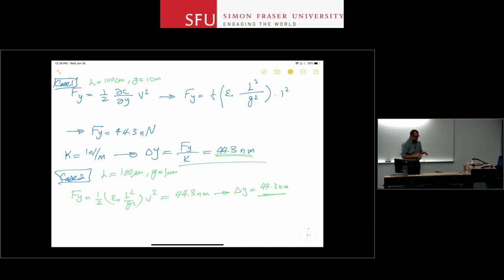Once I scale down the device dimensions to microscales, if you go back and look at our scaling lecture, as long as you keep everything linear, your resonant frequencies go up by the same scaling factor. So if I shrink all the dimensions by 10 to the 4, let's assume that the operating frequency of this movement goes up by a factor of 10 to the 4 as well. So I move these at 1 hertz at macro scale, and at 10 kilohertz at microscale, and I want to see what happens to the output current that you get.